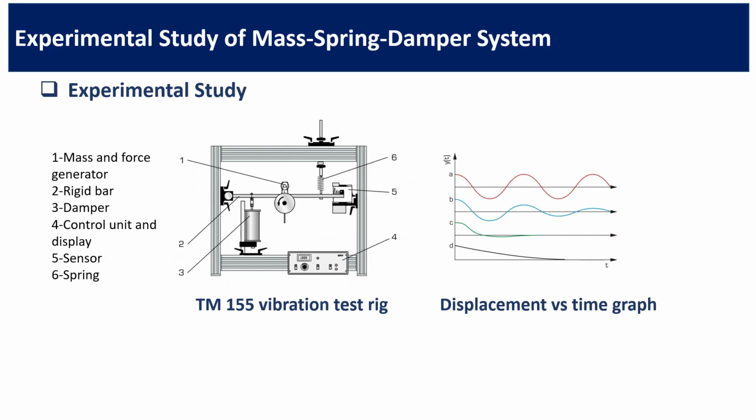In the graph, we can see that A showing undamped frequency, B showing the slow damped frequency, and C showing relatively quick damped frequency. The change in these frequencies can be explained by the different damping media used in this experiment. We can also compare this experimental result, let's say for example the displacement versus time response with the displacement versus time response obtained from the simulation results and find the experimental errors and also identify the cause behind these errors.